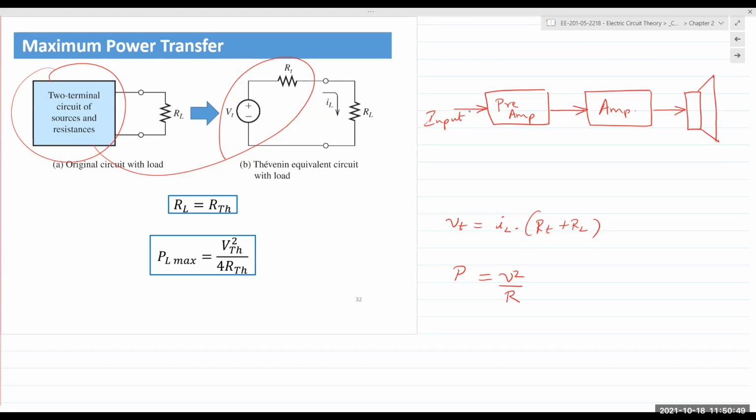When it takes place slowly, the Thevenin resistance of the battery is high. When the Thevenin resistance is high, power is not transferred. When this goes high, power is reduced. That's why you would have trouble starting a car in very cold weather first thing in the morning. And to address that, a car battery will have a spec known as cold crank amps. Basically, how many amps it can supply when it's really, really cold to crank your engine.